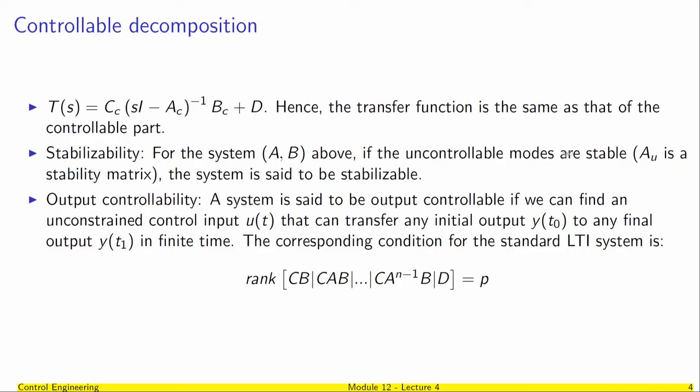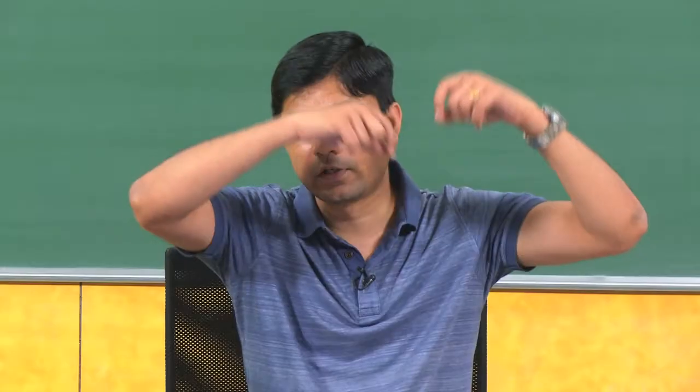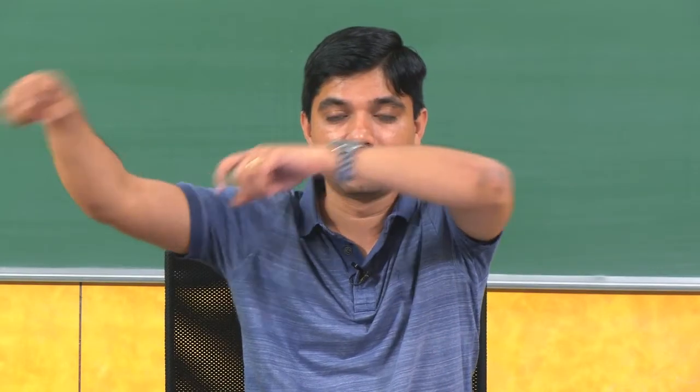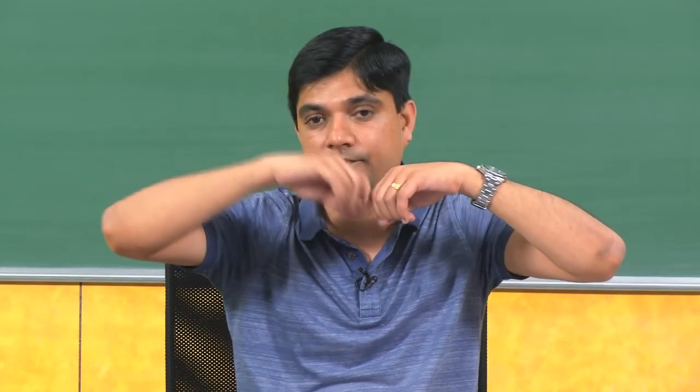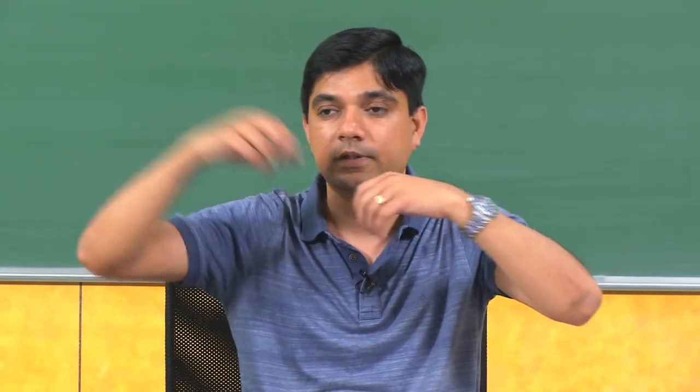Okay. And then a very small extension to the definition of controllability. So far we have talked about the state going from point A to point B in some finite amount of time, and we just relax, saying that the point B is actually the origin. So, what do I say? Well, I want the output to be controllable, not the states, because typically I have x dot is Ax plus Bu, y is some Cx, sometimes some D times u.